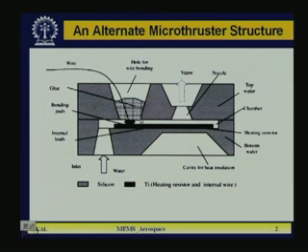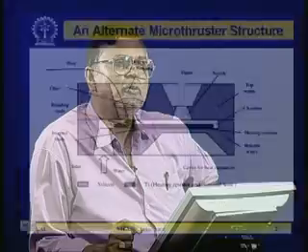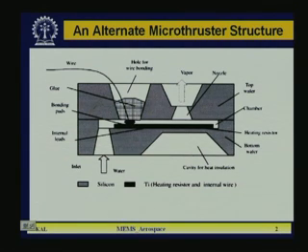One advantage here compared to the other is that with a minimum amount of power you can get maximum phase change and ejection of the liquid. So in that case, the liquid forms gas and that will eject, but an embedded heater may require more power. One disadvantage is that this titanium film which is used as a heater has to be insulated. On top of that, you have to have a certain passivating layer, so that it should not be in direct contact with the propellant.